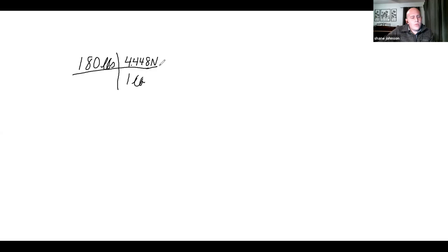And so if I wanted to then give mass, I could convert it. But here, this would give me my weight in newtons. So this would be approximately, well, exactly 800.64 newtons. Now, if I had put a decimal place here, that I had 3 significant figures, which means I would be looking for 3 significant figures in my answer. If I did a calculation that gave me more accuracy than the number I gave in the beginning, I typically wouldn't want to give 5 significant figures when I had only listed 3 in the beginning. So I'd give an answer that's 801, and that's how I would go through listing that.